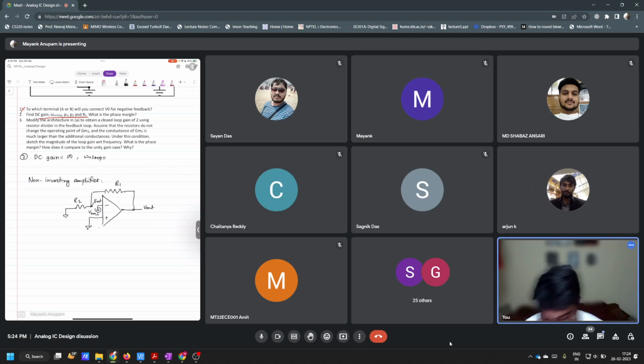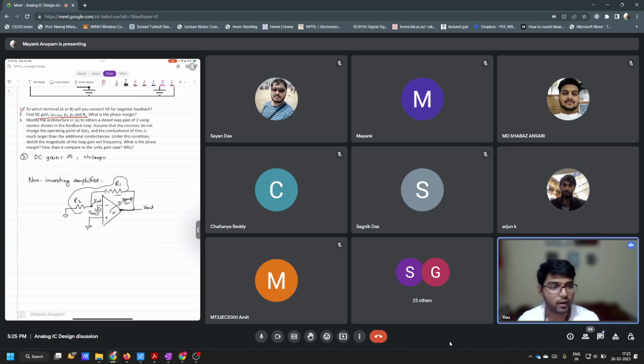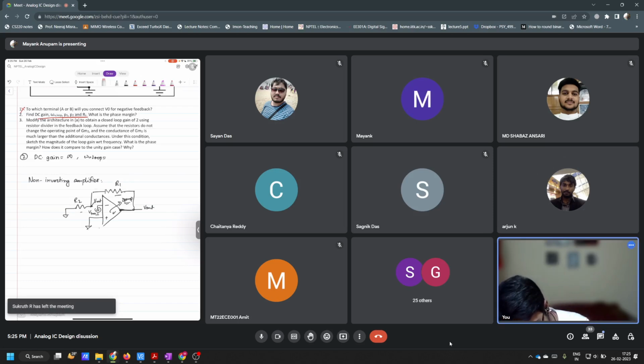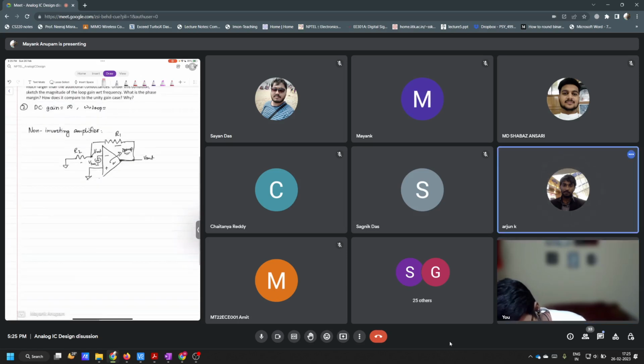But in that case, now at the output of this, let's say this is an op amp. You will have some parasitic gO2, gO, everything inside it also, right? But outside it, we also have these two resistors, and they appear at the output in series, isn't it? So you also have to find and consider its contribution. Is that clear?